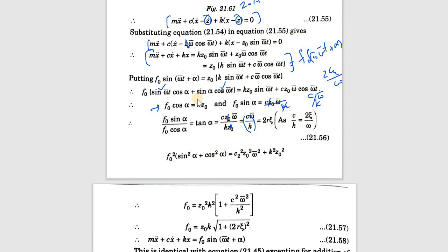Okay, 2 theta by omega. This we already have derived as c by k is equal to 2 theta by omega. So now I can write what is theta. Theta is equal to omega dash by omega. Now, instead of omega, I will be getting 2 theta omega dash by omega. So omega dash by omega is a new ratio. I am taking it as r, that is the ratio of the applied frequency to the natural frequency.